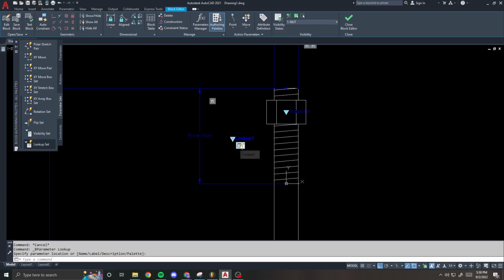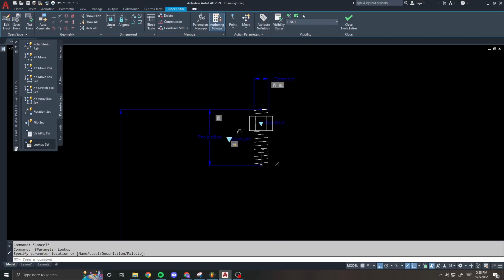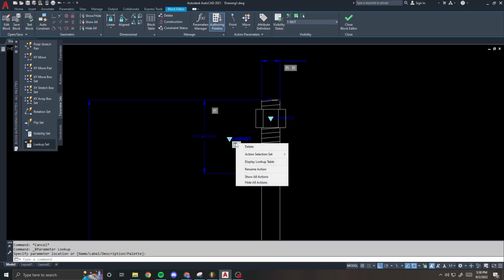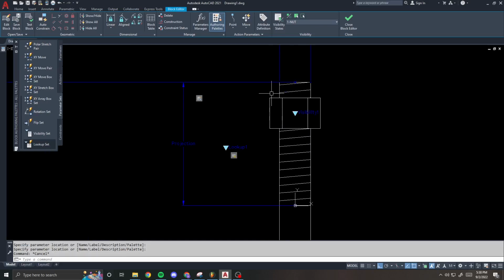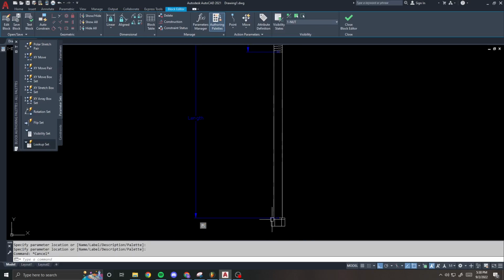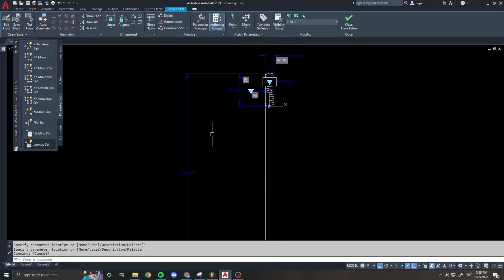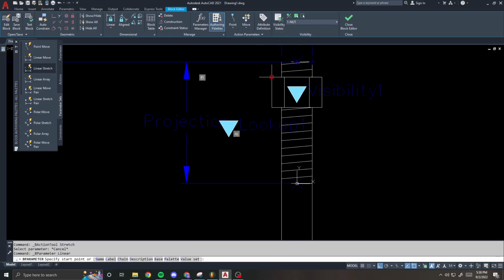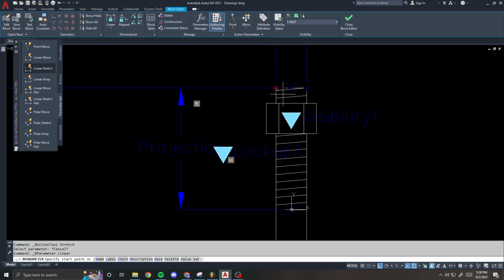Okay? All right, you've got this lookup table. I have all these parameters. I right-click. Actually, I need one more parameter, the nut thickness here and the head thickness. So I'm going to do a real quick linear stretch. And in this case, I want to stretch down. I don't want to stretch up because I don't want it to go past this little buffer that I give it, the 1/2-inch buffer. I want it to go down.